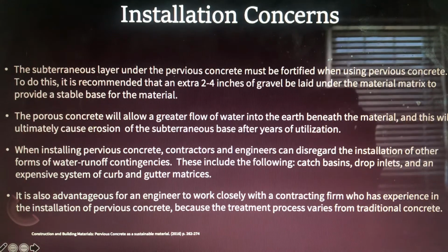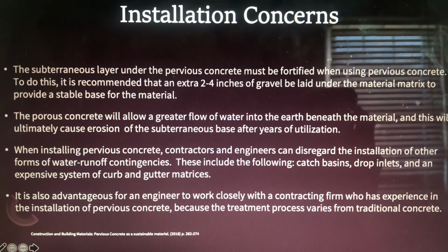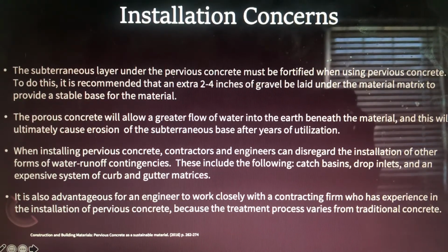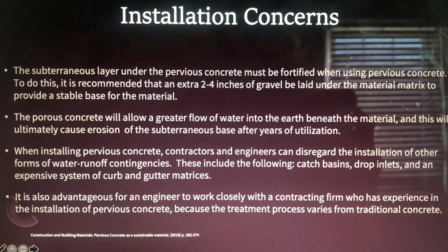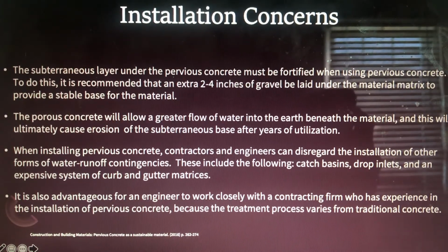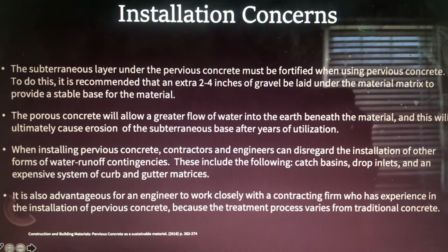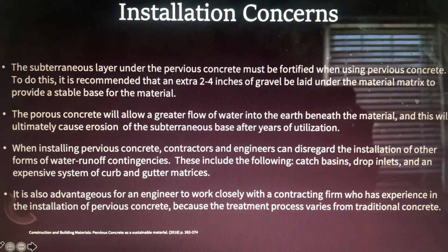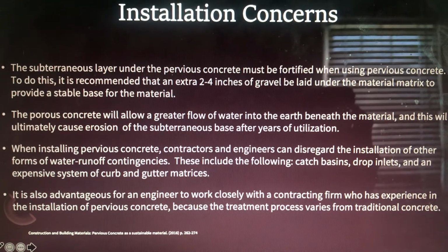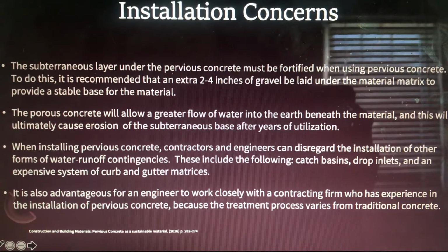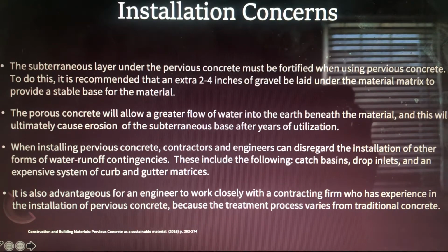The contractor that you employ as an engineer should be well versed in pervious concrete, because the curing and the laying of pervious concrete tends to vary a little bit from traditional concrete, and you would probably want more expertise from the contractor, so we don't have cracking or unraveling showing up from a contractor who hasn't laid pervious concrete before.